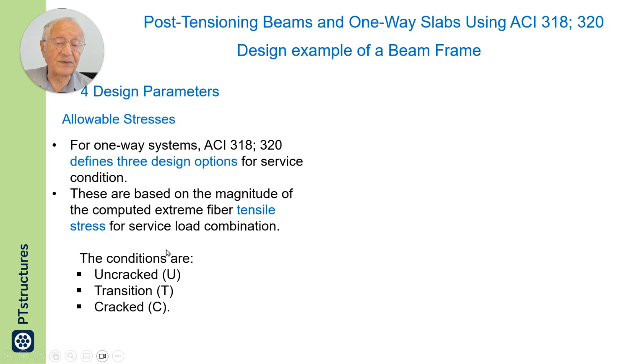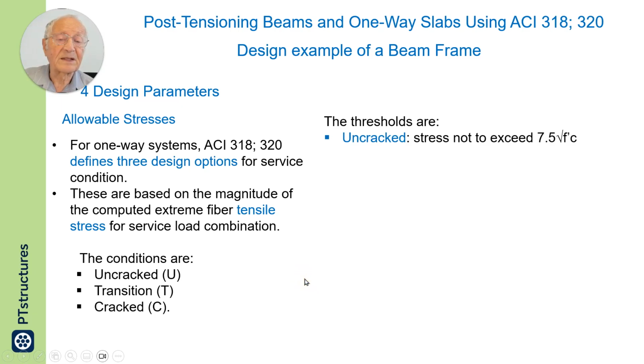The section is defined either as uncracked or transition or cracked section, and depending on which of these stages is applicable, the serviceability design slightly differs.